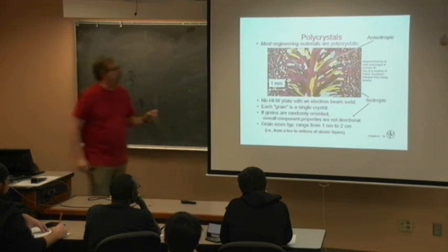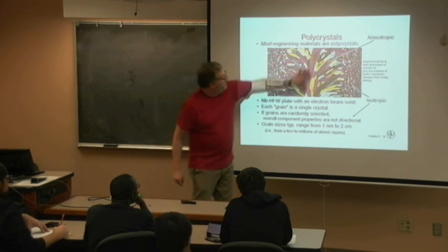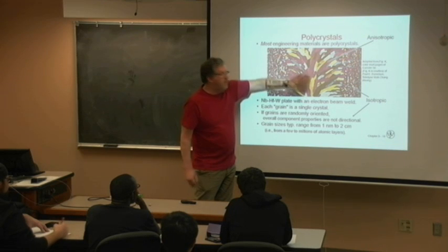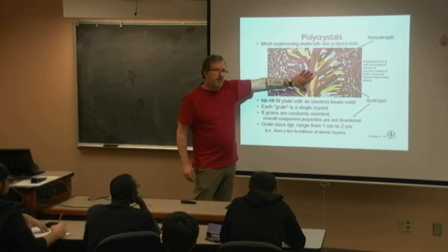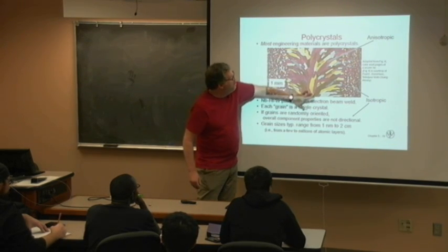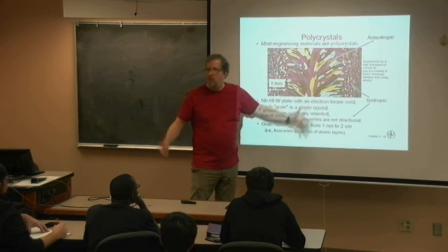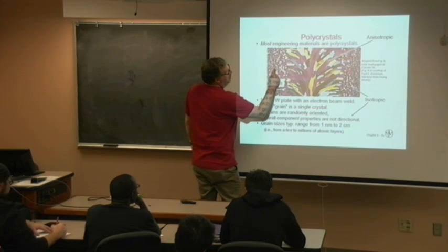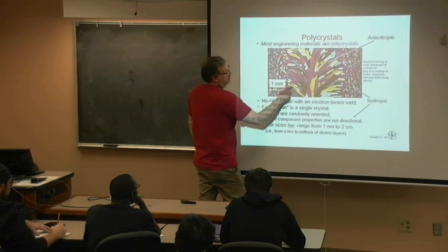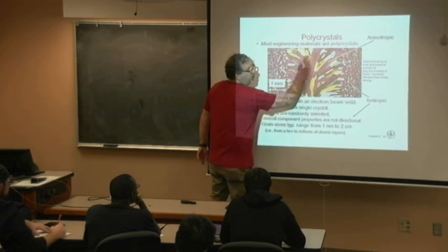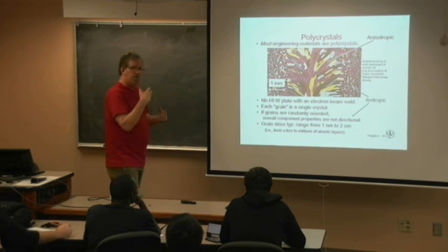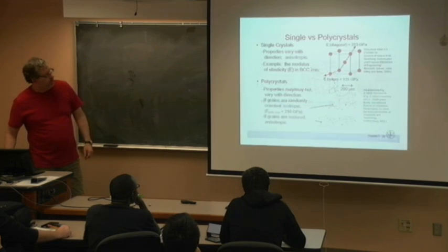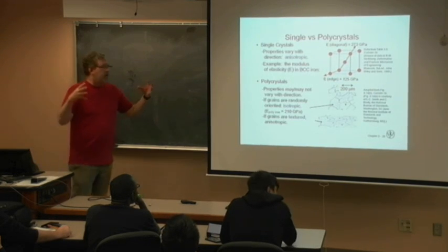This is going back to the crystallography, so you can see, like, this is a weld, but for semiconductors, this was kind of tying into our liquid crystal display, where if I have bigger grains, I'm probably going to have a better mobility, right? Because I have less scattering. You can see the electrons going through this, it's got more obstacles, whereas here it's going to be able to go through these bigger crystals and have a better performance. Yeah, so here. But you put it all together.